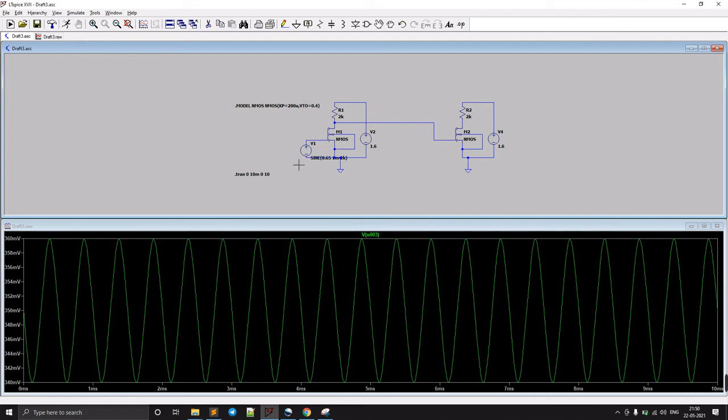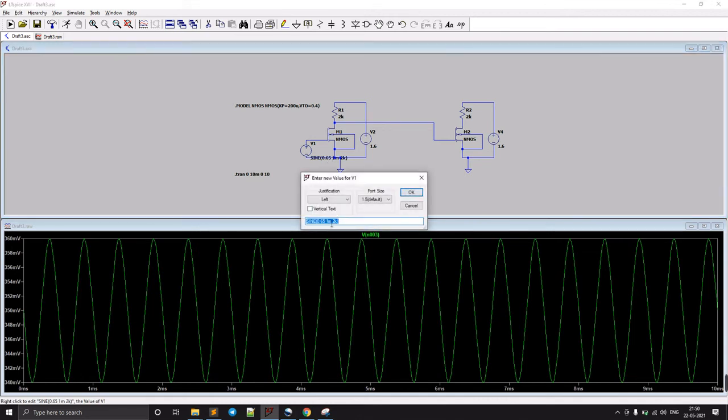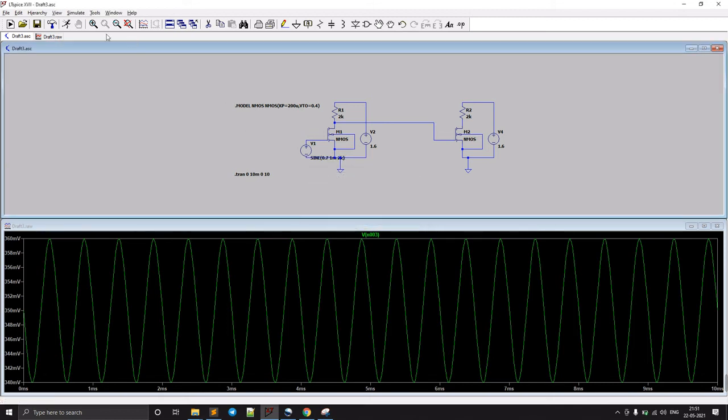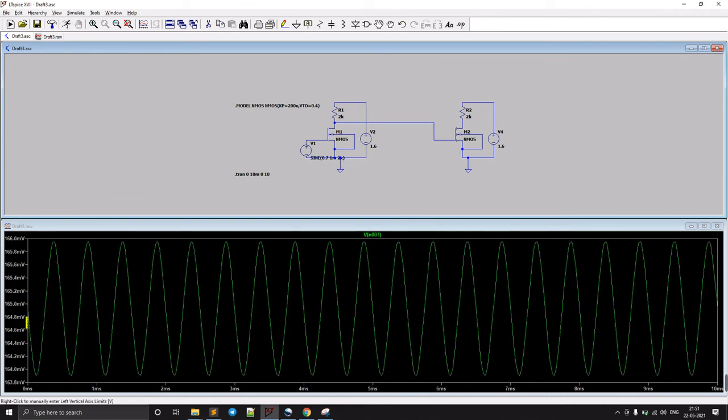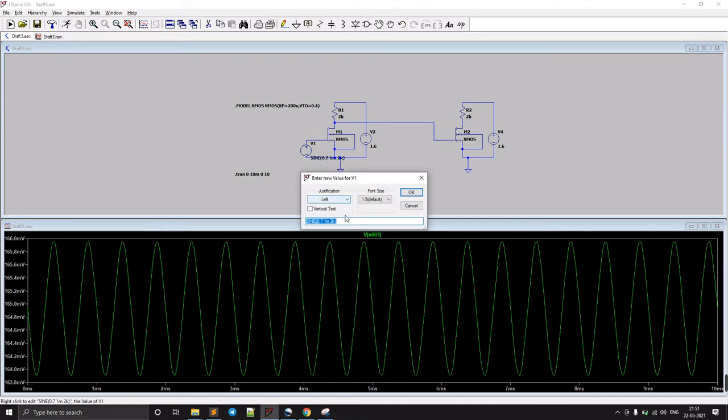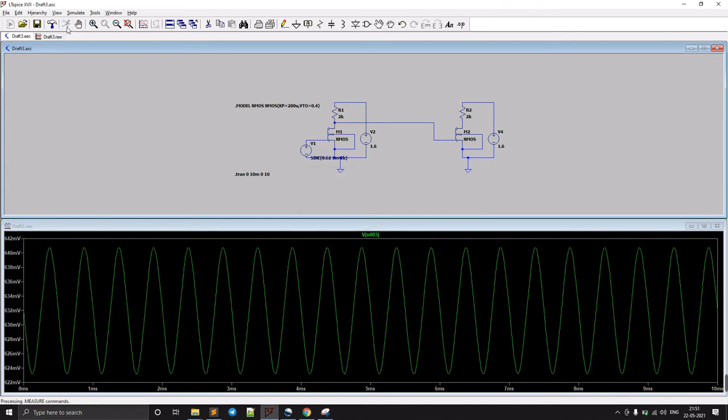So what else can we do now? Let's change this from 0.65 to something else. Let's say 0.7, and we will see how much voltage it produces now. Okay, so this is decreasing. Let's decrease this, instead of 0.65, to 0.62, and check it now. Now we are getting a swing from 32 to 41. So the gain is now 11. It increased from 10 to 11.